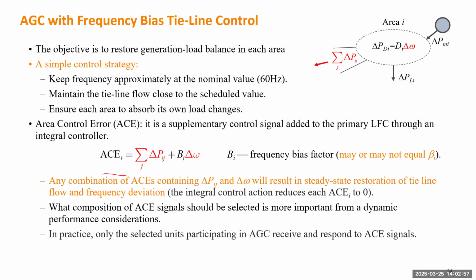Now there's a sudden load increase. First the governor responds, because we have frequency-dependent load D and we have R. The load change divided by D plus 1 over R for the entire system translates to how much the frequency will change. That frequency deviation goes to the generator with AGC.